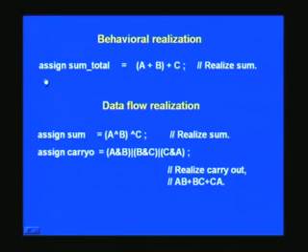And you will notice that in a single line we can realize this full adder, and another beauty of this is that it is irrespective of the bit precision. Suppose you want 16-bit precision for A and B, you can still use the very same statement. The only thing is you will have to declare A and B to be of that precision at the top of the program, which we will be covering later on.